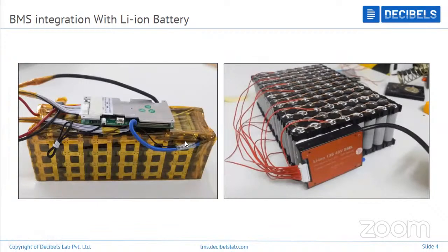For example, let us take that your nominal current is 30 amps only, but the cells used are rated at 3C, which means they can perform three times that for the peak condition. That means it can give up to 90 amps for a certain time duration at its peak condition.